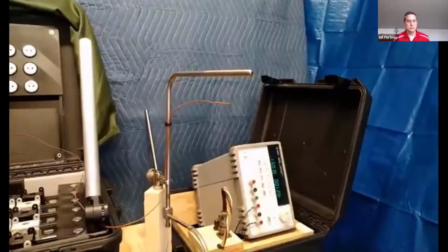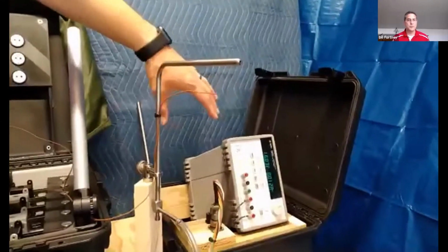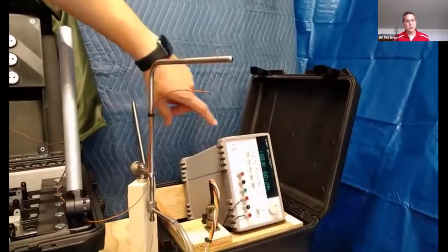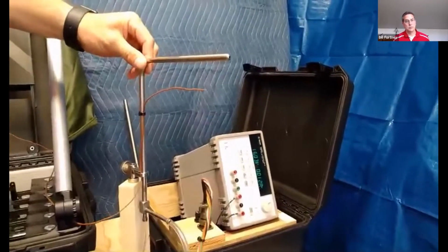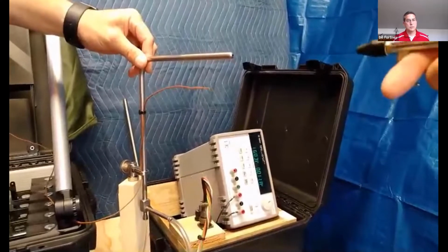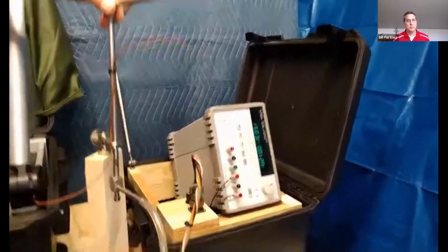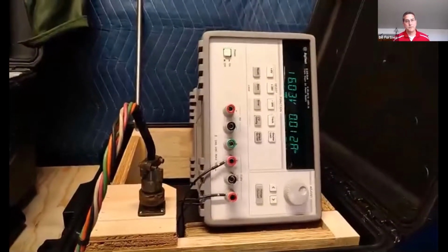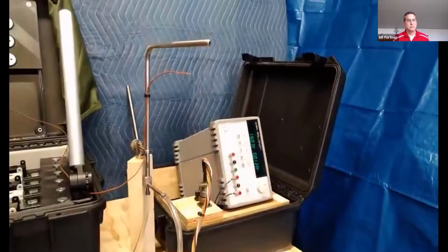We're going to show you a quick demonstration. We're going to blow some air into this pitot tube, and you can see it operates off of an amperage change. So you'll see the amps change right here as the pressure changes. That data would be compiled into our computer program and would show up on the laptop. Our software guys are going to demonstrate that a little later and explain how that works.